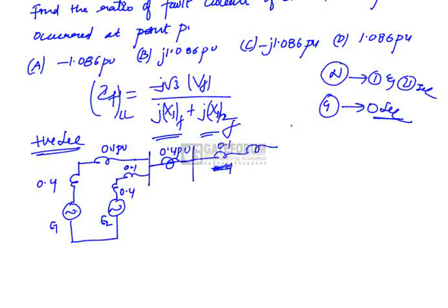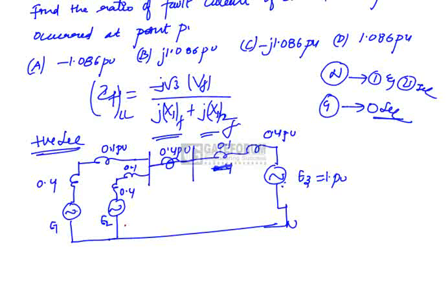In generator we have generator 3 here, so we have to represent it as voltage source in series with reactance. This is neutral point N. Now this value he has given positive sequence 0.4 per unit. Let us take EMF induced G3 as 1 per unit.